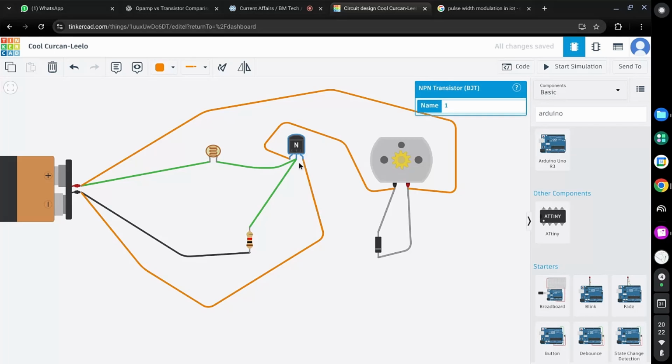So notice this BJT here is current control. A MOSFET would be voltage control. Whether the circuit turns on and off, you want to use voltage to control it or current to control it. That determines the choice. In this case, notice your source is a voltage. I can control the voltage here, I put a voltage divider and I can control the current there. So I used a BJT. You could also do this with a MOSFET. Okay, point number one.